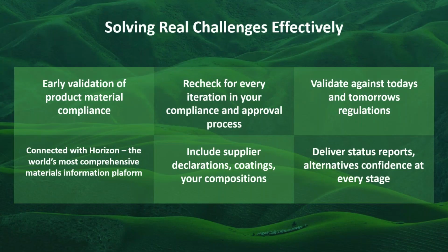So what does Green Line actually do? Well, it can help you validate the compliance of your entire bill of materials, or BOM, as we will refer to it, by helping you carry out a simultaneous assessment for approximately 100 metallic and non-metallic materials against more than 20 regulations which we have available. These, of course, include the major European ones, such as REACH and RoHS, but also GADSL and WEEE, just to name a few. Also, Green Line can allow you to carry out an entire life cycle assessment so that you can determine the whole environmental impact of the different materials which you may be using in your project design.